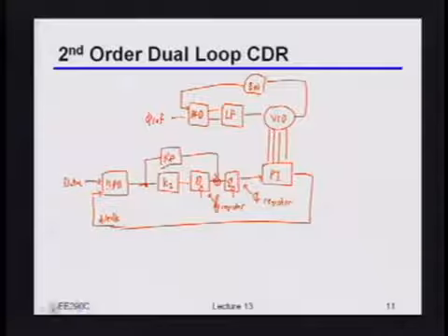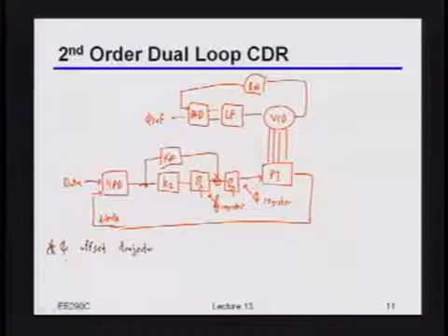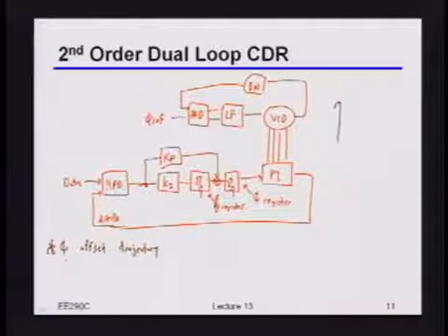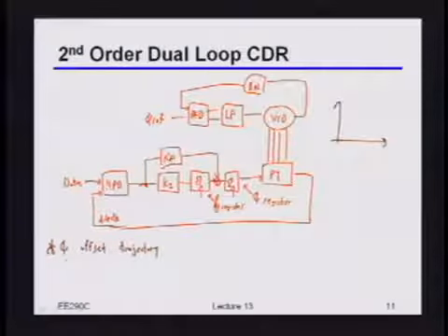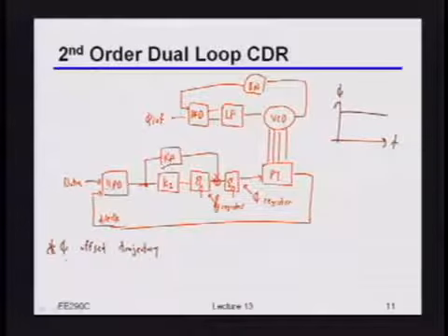Okay, so the higher order bit to keep in mind here is that whenever you're building these CDR types of loops, the really important thing to look at is the phase offset trajectory. By trajectory, I mean that in a mesochronous system, the phase versus time is basically constant, so it looks like that. That means that when you build the loop, a first order loop is fine, because you just have to figure out what that offset is.